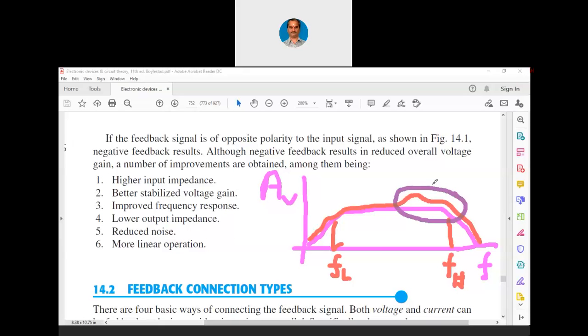Now, what do you understand by this particular point where the gain is increasing? When the gain is increasing at a particular given frequency, let us say in this particular frequency, gain is increasing here. Now, the gain is increasing, that means that the net impedance of the circuit is reducing. When the impedance is reducing, suddenly gain can increase. Now, we thought that impedance is supposed to be constant throughout. But at higher frequencies, impedance also need not be constant. Why? Because at higher frequencies, parasitics are coming into picture.